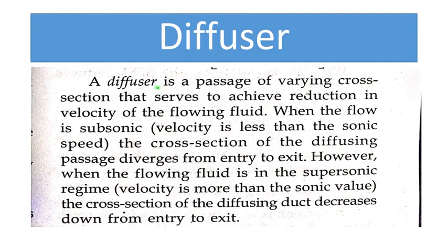Now another case is that of a diffuser. A diffuser is simply the reverse of a nozzle. In a diffuser, the velocity of the fluid is reduced at the expense of an increase in the pressure energy, or we can say the pressure energy or the enthalpy of the fluid increases at the expense of velocity.